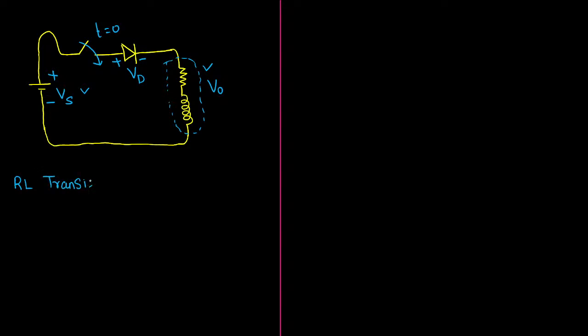So definitely you will be observing the nature of transient behavior here, because it is an RL circuit. The inductor is there, it will be playing a role. So the first step is to find out the current flowing through the inductor, IL of t. Since inductor, resistor and supply are all connected in series, the current through the inductor, the current through the resistor and the current through the supply are all equal.